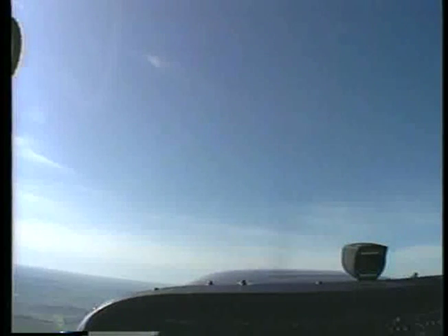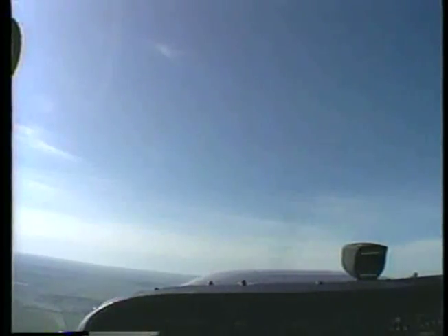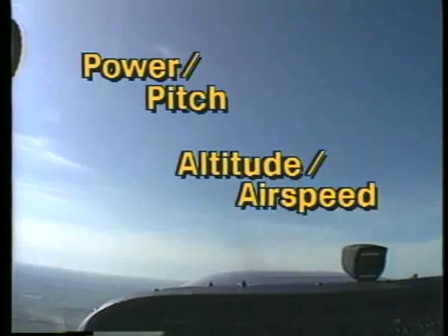You should practice maneuvering during slow flight to develop a feel for the controls at various speeds and power settings, and to learn the relationship of power and pitch to altitude and airspeed.